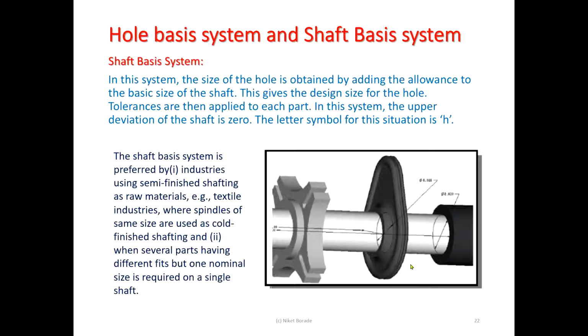It will wear out, you have to change it, because generally they are made of ceramic or sometimes metal, and while the thread is passing, large heat is generated, and there is always friction there, while the thread is passing on the machine looms. We're talking about textiles here. So you have to change only this part, you don't have to change the shaft every time. Some of the thread guides may be rotating like a roller, and some of them may be fixed to give direction to the thread.